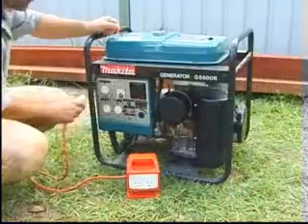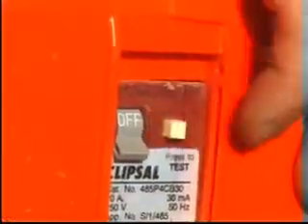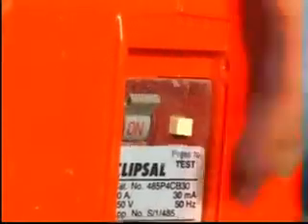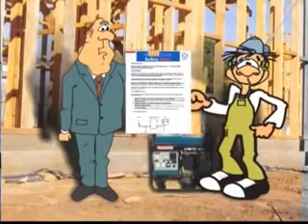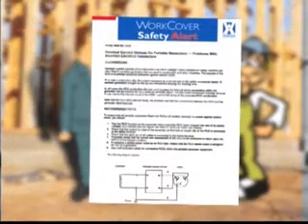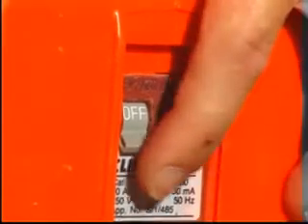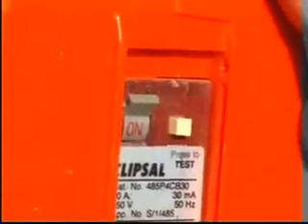In a work cover safety alert, authorities have pointed out that earth leakage device protection may not work with generators. While the earth leakage device test button may appear to indicate there are no faults, it only monitors the internal circuitry of the device itself.